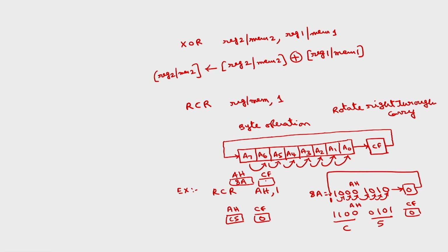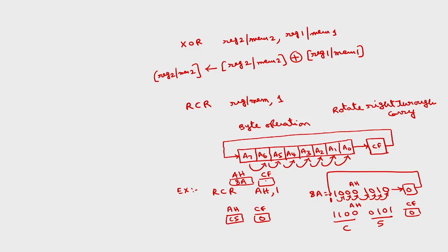So, for the contents of a 16-bit register, the similar operation will take place. The contents of A15 will become the contents of carry, and A0 will in any case transfer to the carry flag. Okay. Similarly, we can have this as a byte from the memory location or word from the memory location. This is if you want to shift by 1 bit position. If I want to shift by 4 bit positions, instead of writing this 4 times, we can directly mention that 4 into a register called CL, which is an implied register. So, for single bit rotation we have to mention 1, for multiple bit rotation you have to write